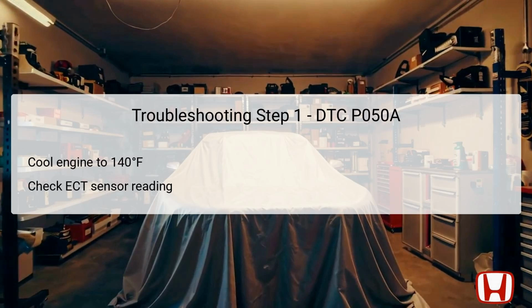Before proceeding with further diagnostics, verify that the ECT sensor is reporting accurate temperatures to the powertrain control module, PCM. An inaccurate sensor reading can falsely trigger or prevent the correct monitoring of the cold start idle air control system. This accuracy is paramount for the subsequent steps in the troubleshooting process to ensure the correct diagnostics of the vehicle's condition.